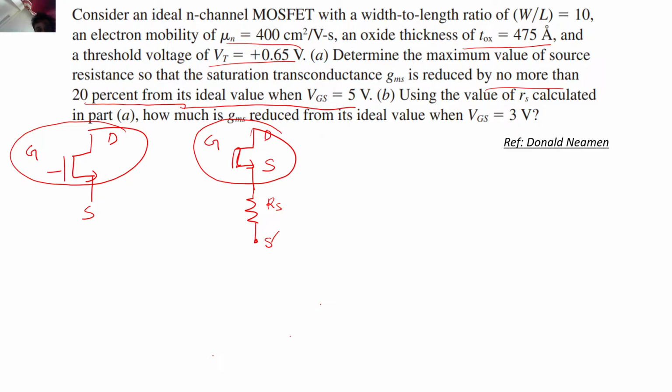That is, this is the first MOSFET, this is the second MOSFET. Now can I give the input at S instead of S dash in the second MOSFET? The answer is clearly no, because this resistance is coming from the N plus region at the source side. I just told you there is a resistance in the drain and source regions, so we cannot separate out this resistance, and whatever input I have to apply is at the node S dash. This is the only thing that they are saying.